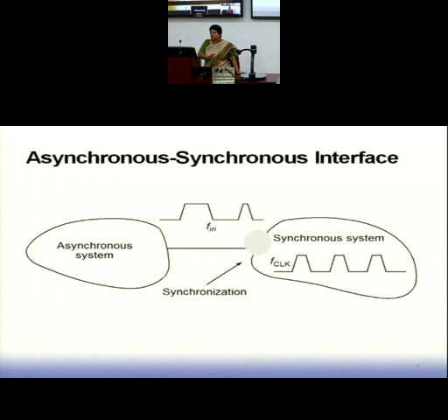Now it so happens that while it is fed, since there is no timing attached to it, it can come at any point of time, very close to the system clock edge. Now think of a data path which is, say, positive edge triggered, and suddenly an input comes after the T setup, which gives you a T setup violation or a T hold violation. Because every system has to go through a flip-flop, a pipeline system, naturally it is violating either a setup time or a hold time.